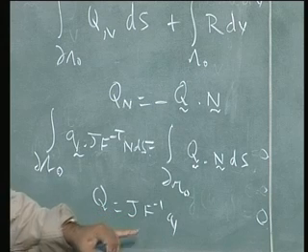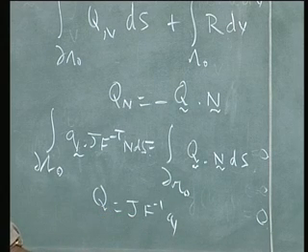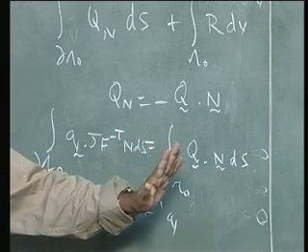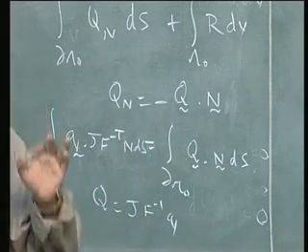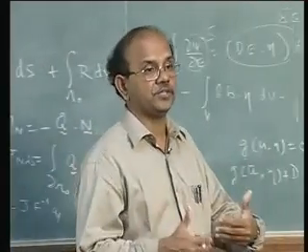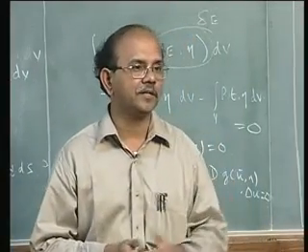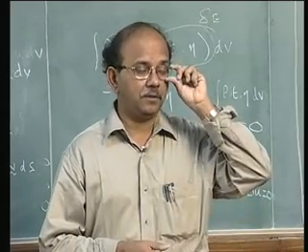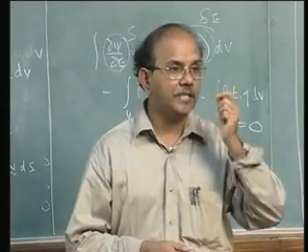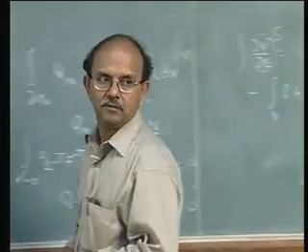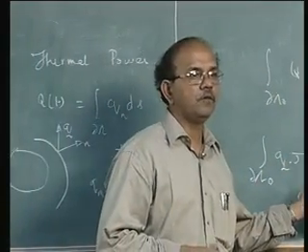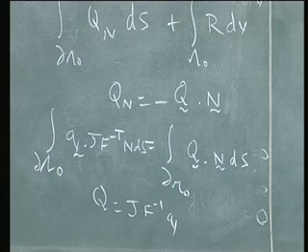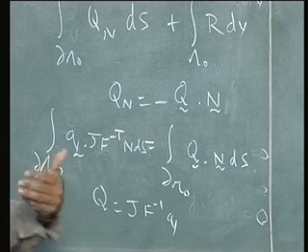Here F is still the deformation gradient? Yes, F is of course the deformation gradient, and what I have essentially used is to relate d small s and d capital S, which are related by the deformation, and hence obviously the deformation gradient comes into the picture. So the first Piola-Kirchhoff stress has an equivalent in heat transfer, which we call the Piola flux, and sometimes people call this the Piola transformation from one to the other.